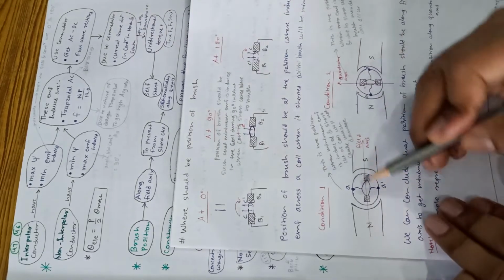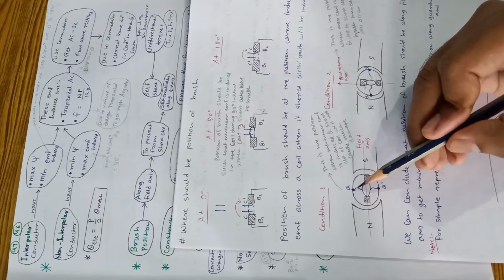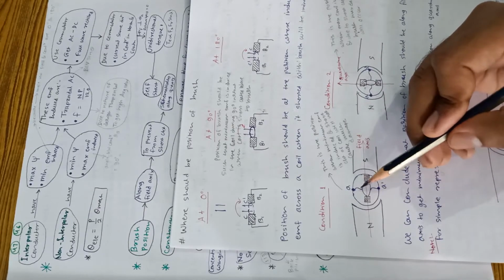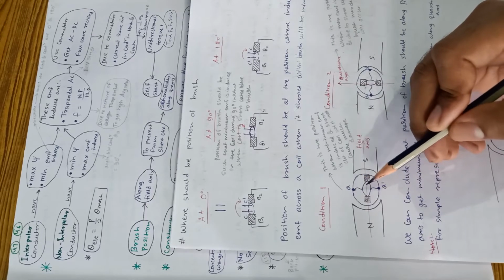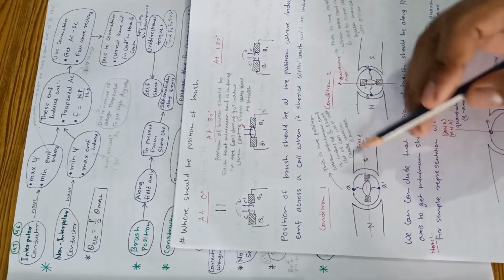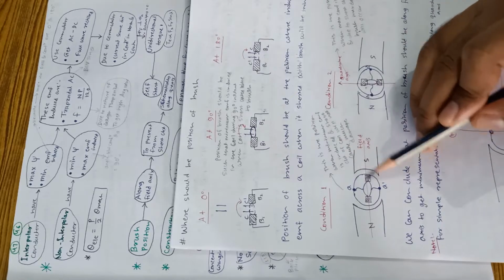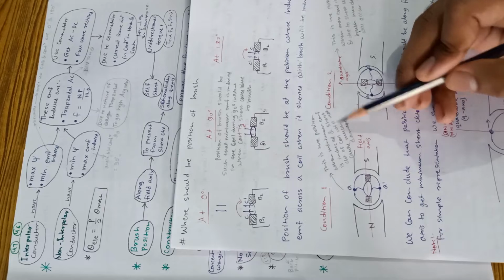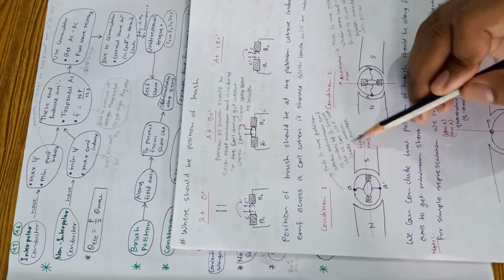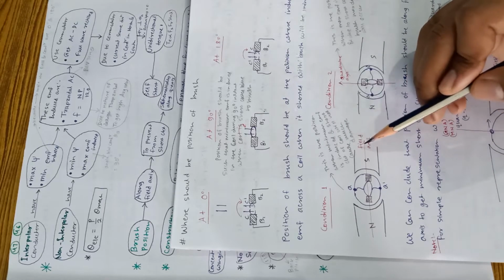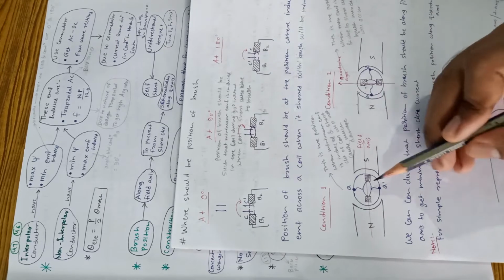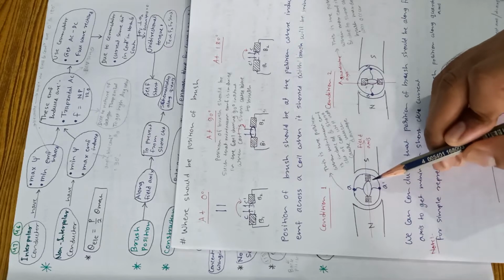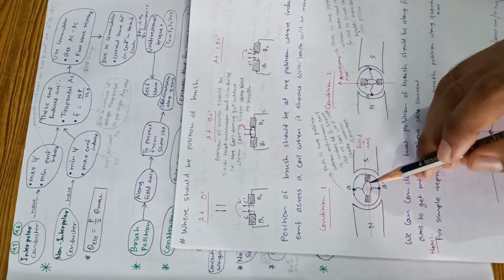See why it is kept in the field axis now. If it is on the field axis, we know that the interpolar conductor has minimum EMF induced. This is the position when minimum EMF is induced, and short circuit of the coil will not damage the coil, okay. If we short circuit the coil when the minimum EMF is induced, then no current will flow, so the windings will not get damaged.